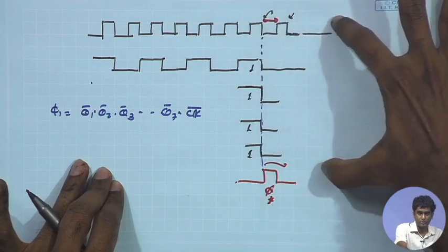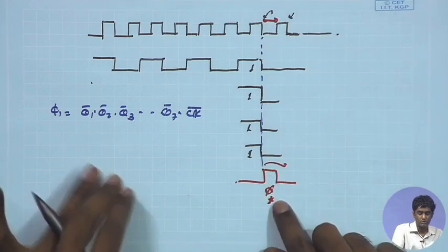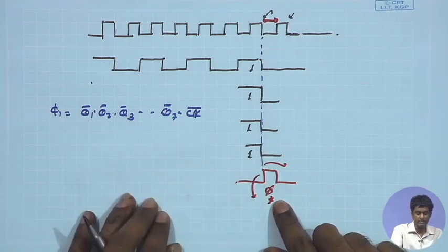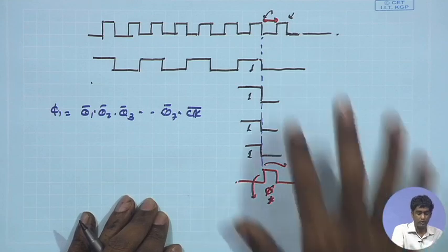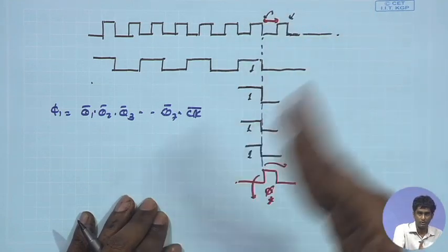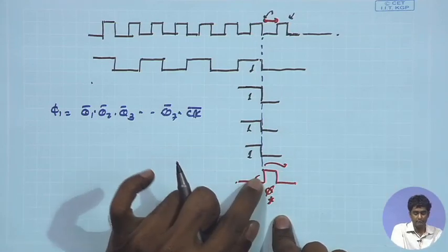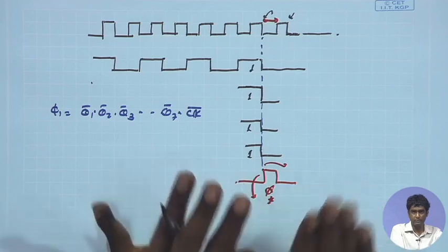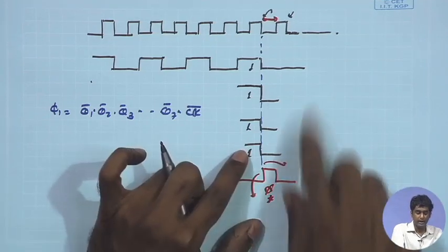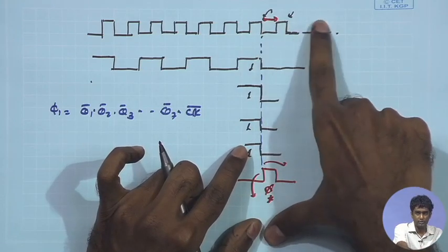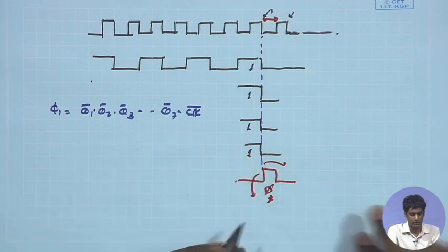for longer duration. It is not counting for a longer duration, and also you need to have another scheme which is going to count how many phases of the clock you want for the phi 1 duration. For example, when the phi 1 goes high, after that logically what should I do in order to extend phi 1 further? I should count how many clock pulses of the original waveform you need for phi 1 to be high. So, if I want to extend phi 1, right.